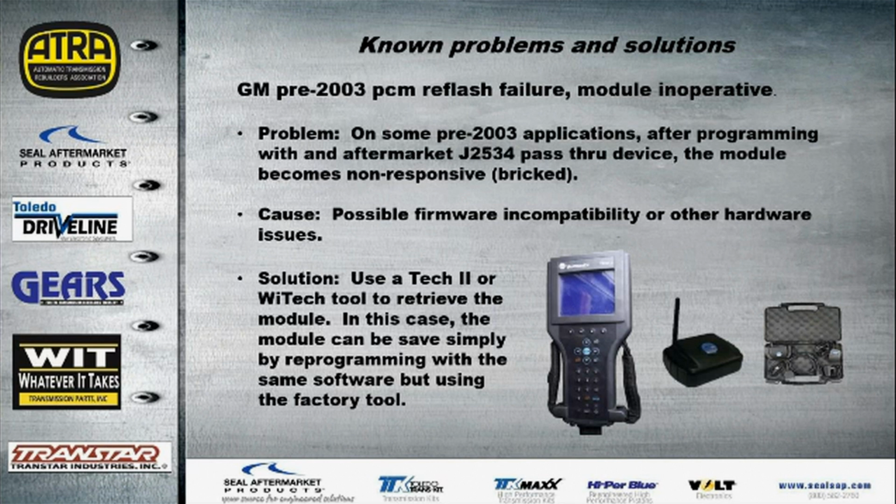In this case, we could possibly have a firmware incompatibility or other hardware issues. There's a lot of coding that happened pre-2003 that didn't continue through and was discontinued, and it can cause issues and can actually blank out a module. In this case, we can bring it back to life. We don't have to throw it away. We can bring it back to life using a PT2 or a Y-Tech tool.